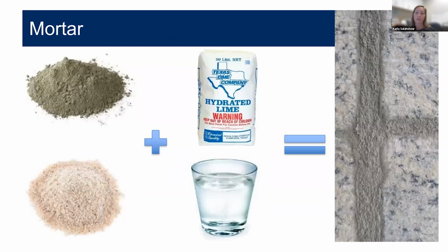So if we talk about mortar here, mortar is also a hardened material similar to concrete, but without the larger coarse aggregate. The paste typically includes a blend of Portland cement and hydrated lime, although we have seen mortars that contain solely natural cements, lime sand systems, that had slag cement even, and just many other blends have been used for mortar.